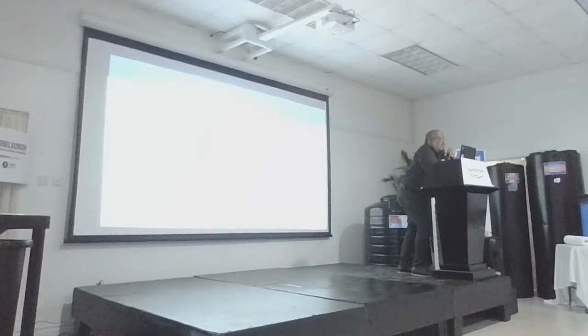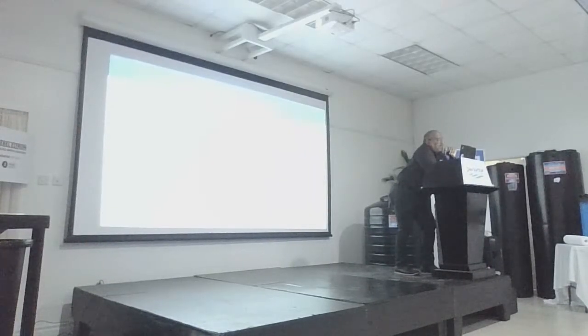Different territories have minimum gallonages, as we found that in St. Lucia, the minimum gallonage allowed is a 750-gallon septic tank and greater. Different territories use different ways to measure what is required. Here it is gallonages and holding time.